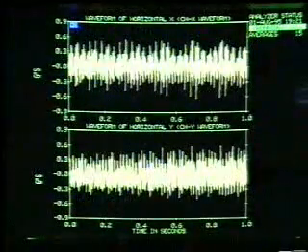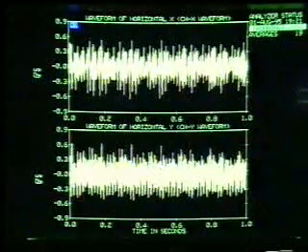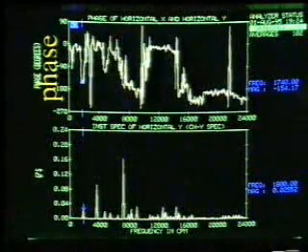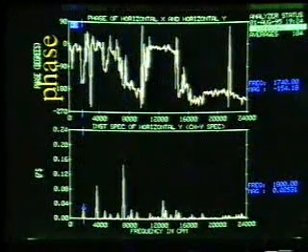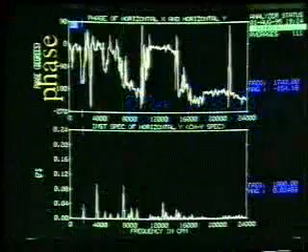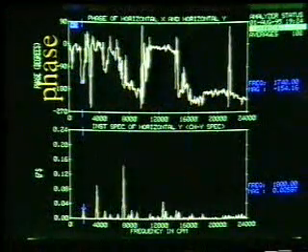The waveform energy may seem to be very busy and intimidating for us to perform any calculations, but the analyzer can display the data as a spectrum. Then we can select a particular frequency of interest and have the analyzer display the calculated phase relationship. Notice that we can select any frequency in the spectrum for the phase comparison.